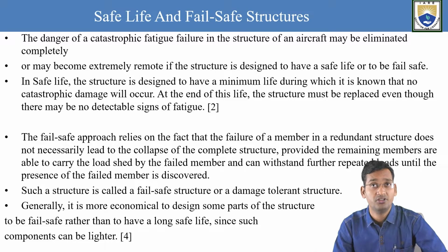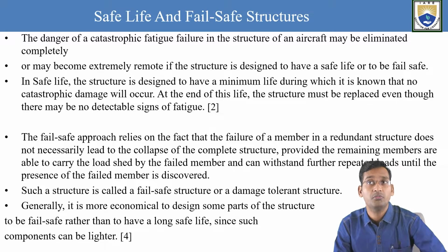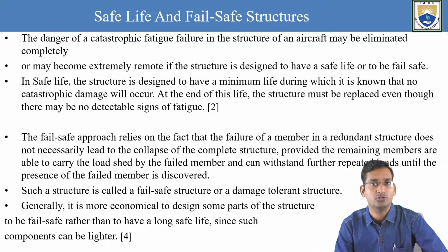So in that fail-safe approach, what is that? The fail-safe approach relies on the fact that the failure of a member in a redundant structure does not necessarily lead to the collapse of the complete structure. Means it's not necessary that you have to completely change the structure. Just as you can change the refill, similarly here one or two members of that structure, just replace them.